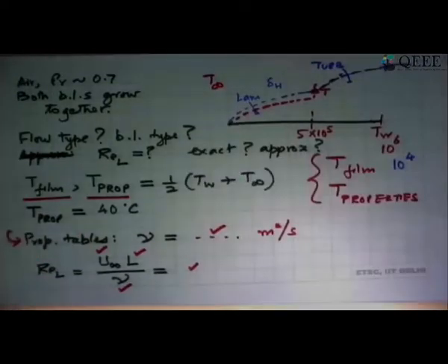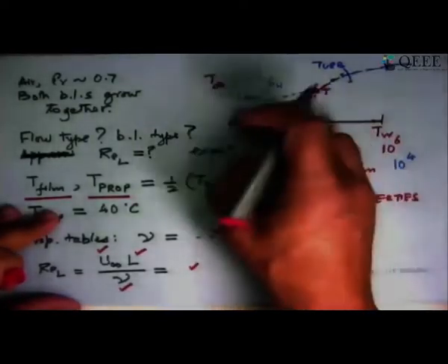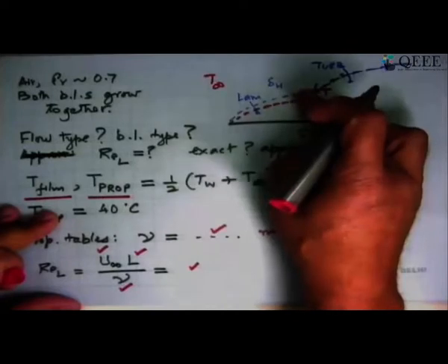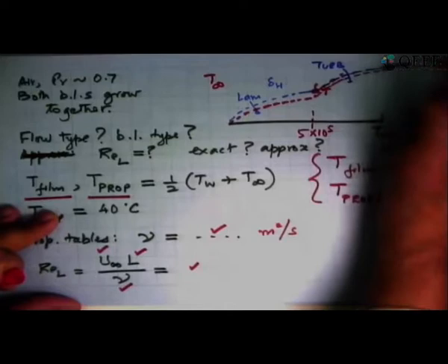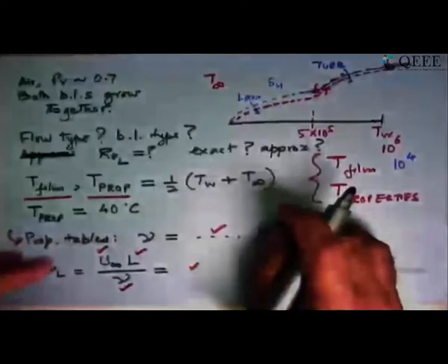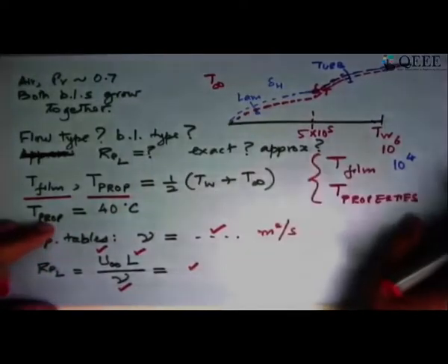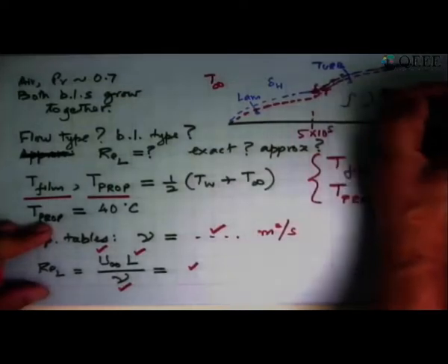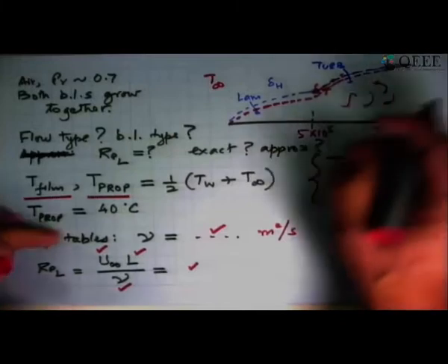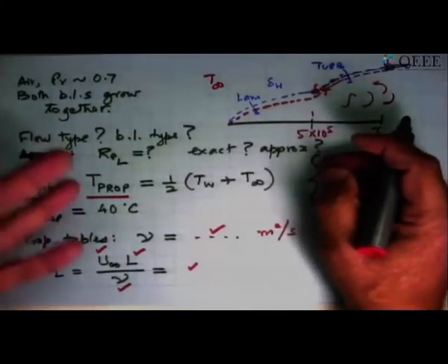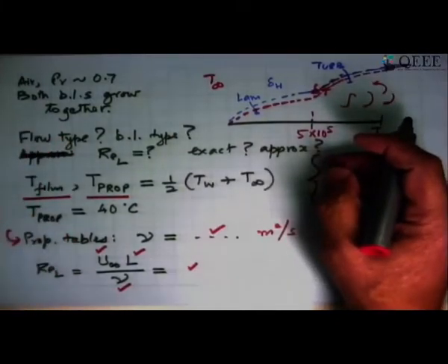The next thing is what happens to the thermal boundary layer. In the case of laminar boundary layers, both will grow together. In the turbulent case, the thermal boundary layer will now become almost exactly the same as the hydrodynamic boundary layer because of mixing taking place there, the fluid getting mixed up. Wherever mixing is there, the hydrodynamic boundary layer is there, and because mixing is there, temperature equalization is there. So the two boundary layers will be very close to one another once the turbulent flow sets in.